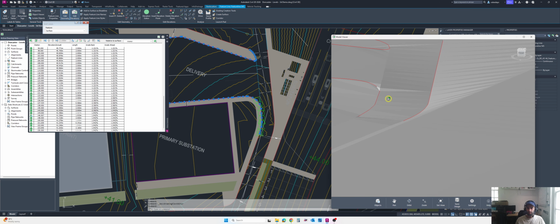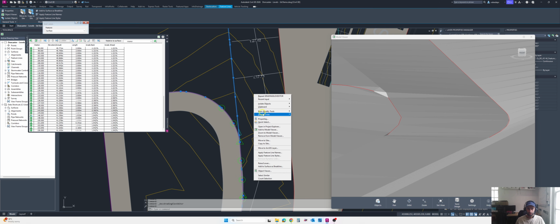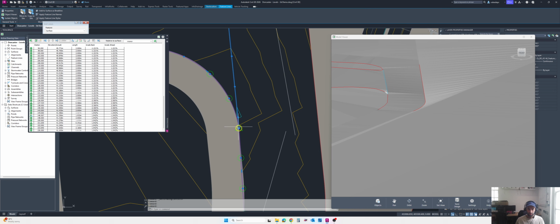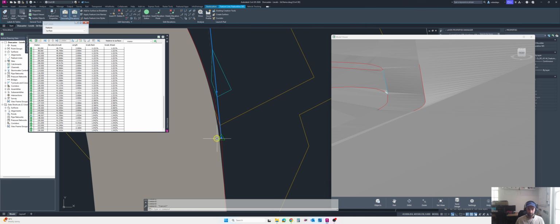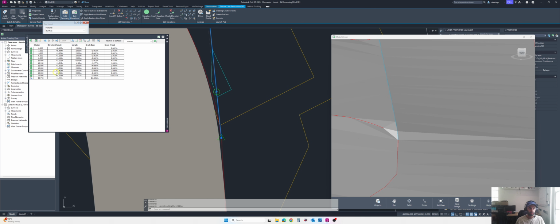And we can see it's almost good, but this one we still have a bit of an up point. I think it's because of this feature line I have here. So add to model viewer, yeah. So now I have this point and I can create this point to that point. So my blue line has the elevation 41,351. Yeah, and then this one is, let's say, quick editor. Yeah, 21. So I can fix this by selecting my feature line.